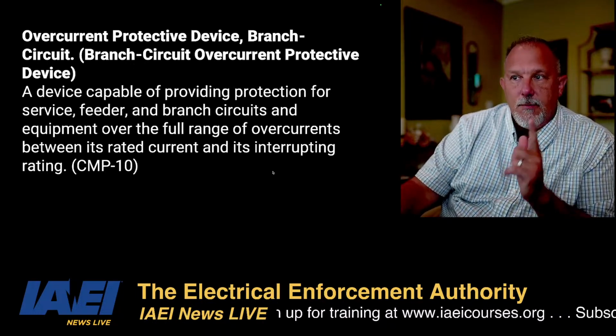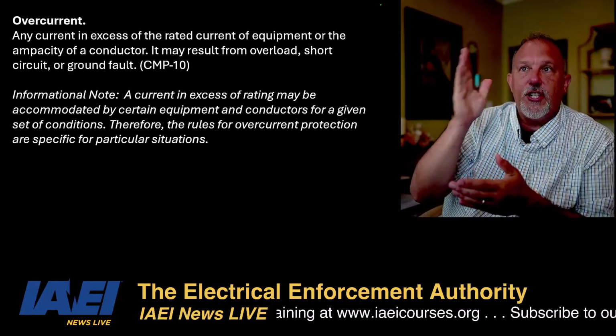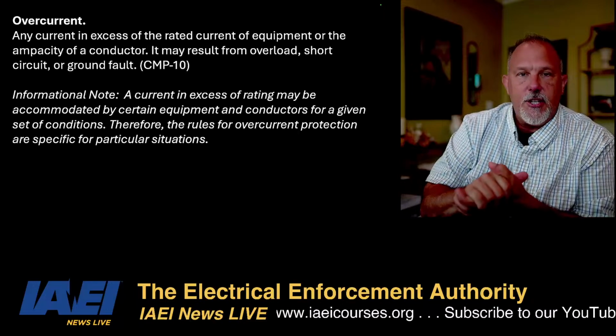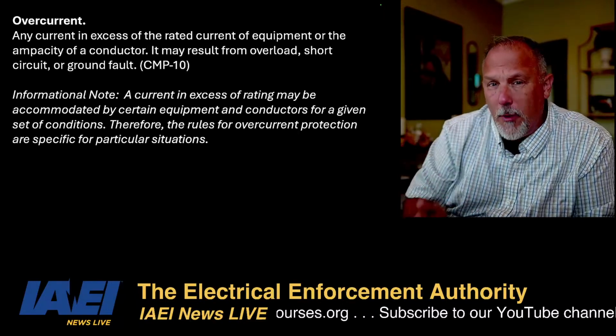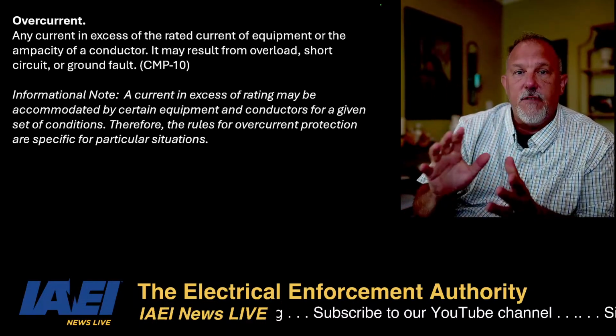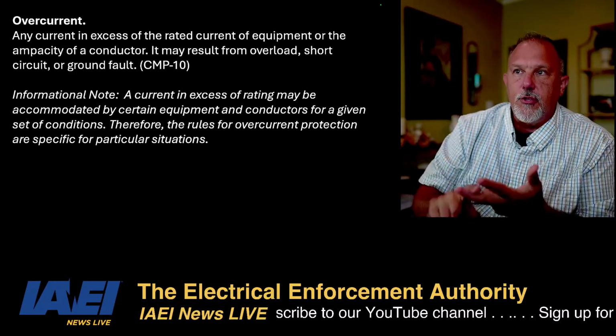Now, some terms to keep in mind that are in the code. We have the definition of an overcurrent. That's any current in excess of the rated current of equipment or the ampacity of a conductor. So we're talking equipment and conductors in this definition. That could result from an overload, short circuit, or a ground fault.